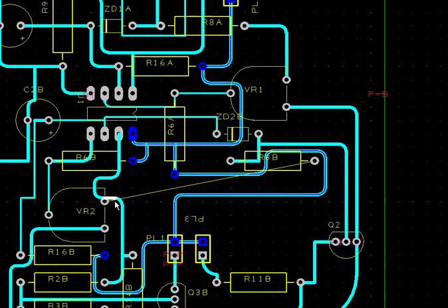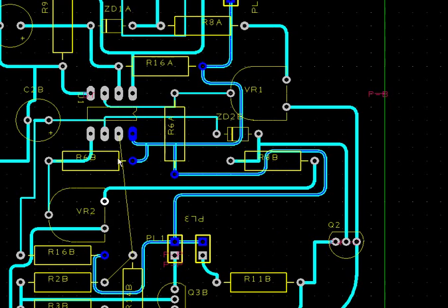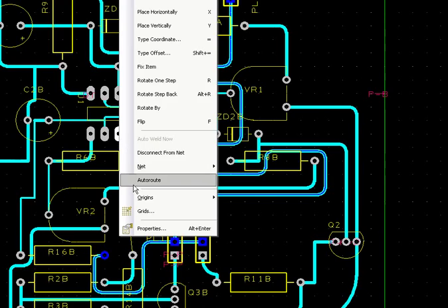I see what's happened. It's because I'm moving my variable resistor. So let me just undo these. Tidy up the clutter and redo them. Right, I'm just going to connect this one first because that's going to get blocked otherwise. This one goes straight across over to here, so let's just route this one. Now this one is going to have to be routed around this variable resistor. Oopsie, it's gone down here but not up here. Right, let's try up here.